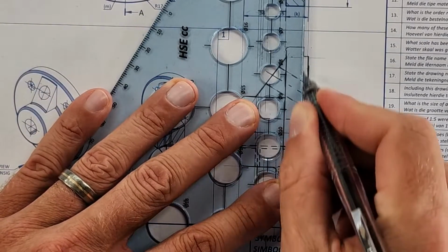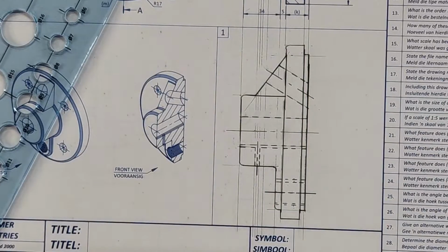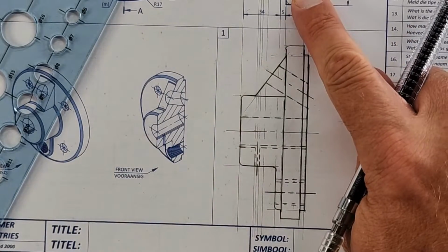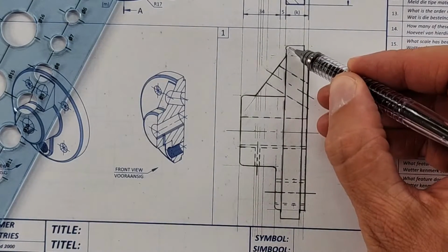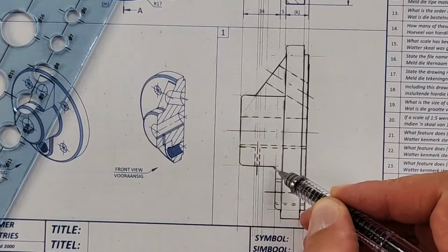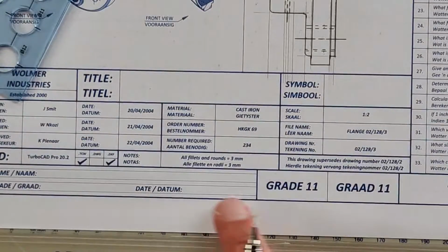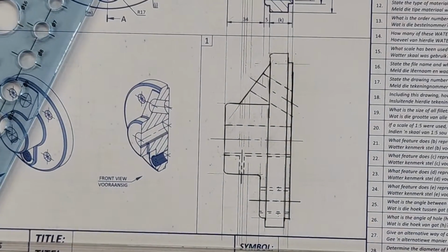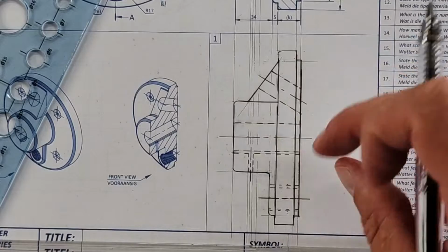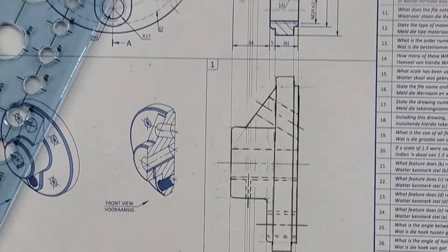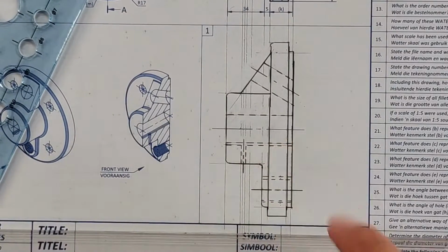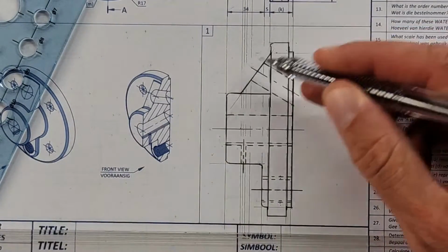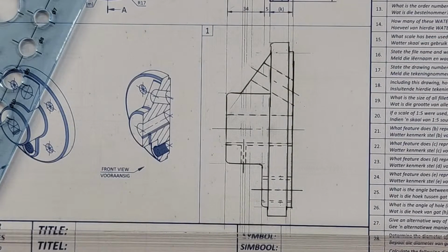Okay, so, right, I'll just refresh you. There's my external view of our flange. The rounds and the fillets are all specified at the bottom as radius 3 millimeters. I just drew this so that you have a memo when you're drawing this yourself. You're going to get all of this hidden detail from the right view that's given, and you have to make sure you draw them as hidden detail, not like I did the first round, and finish that right view of the flange.